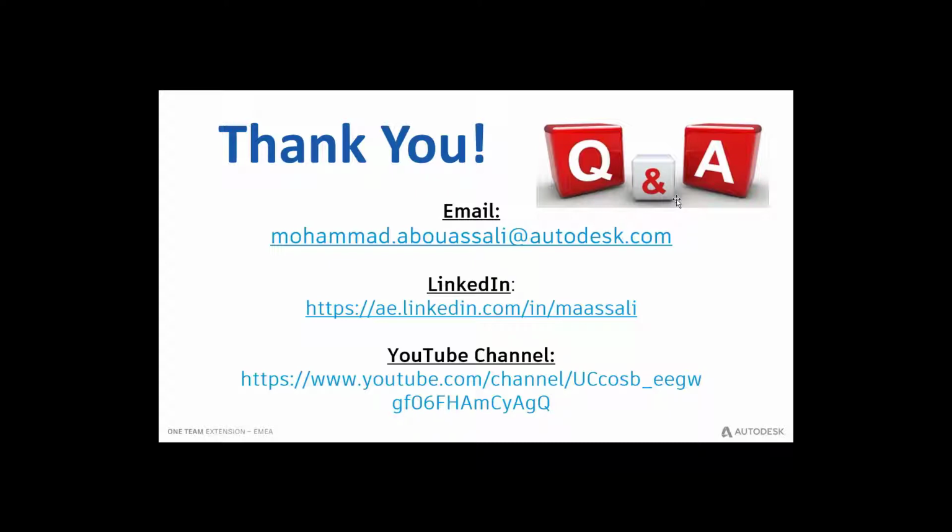Yeah, I know. As far as I know, we don't have tools to calculate where these are supposed to be, but you can leverage the tools we have right now to place them at certain intervals, or else use them from the library of InfraWorks to place them at certain locations where you find they're necessary, and then you can use the other tools in InfraWorks to quantify them.